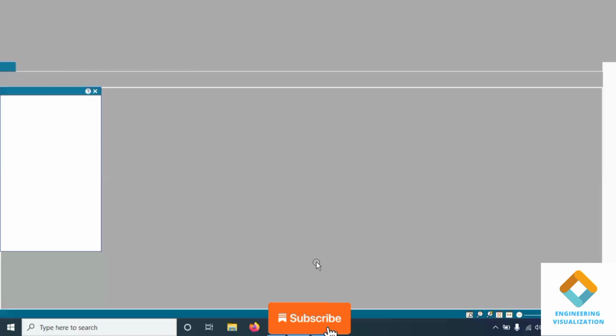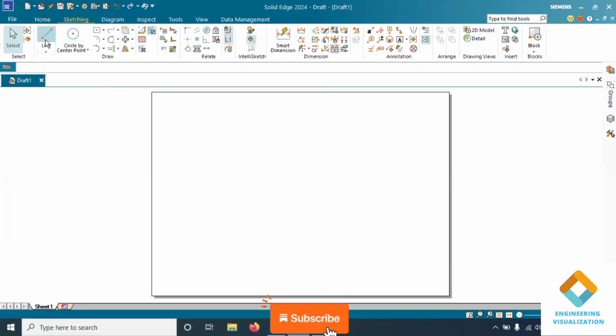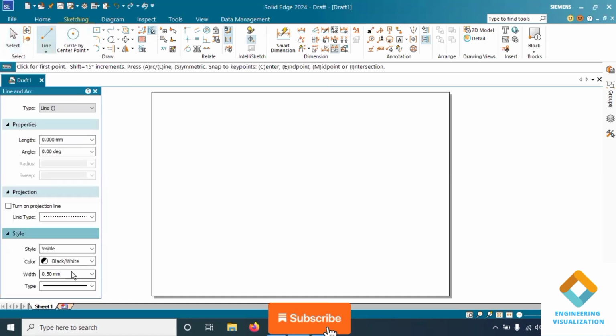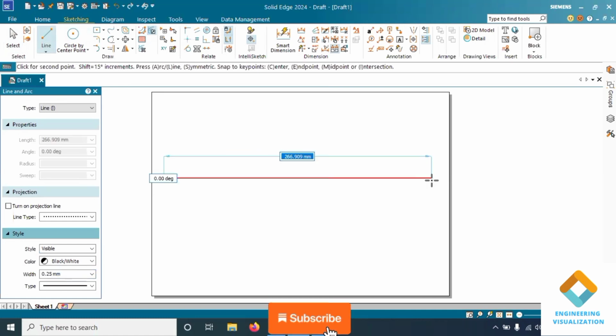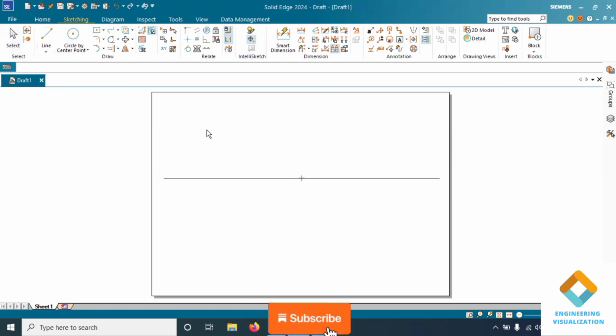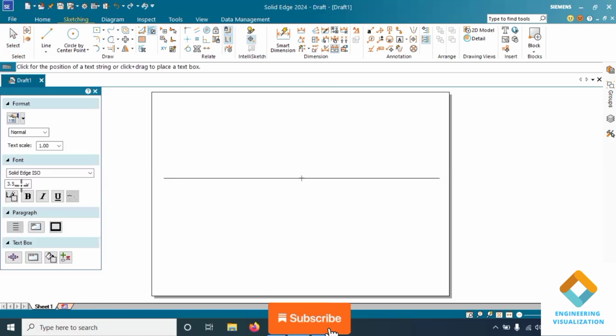In this problem we have to use the dimensions of the ellipse, that is the major and minor axis. The circle dimensions they have not given, and it appears as an ellipse in the front view, so we need to use the major axis of the ellipse, 60 mm, in order to construct the circle. This is one of the special types of problem. In this problem they have not given any kind of inclination. We have to use the data given in the problem to solve it.